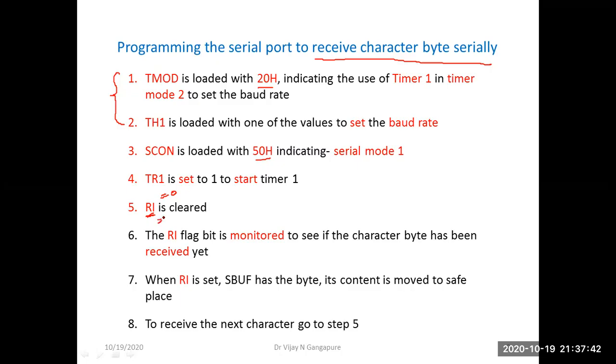So while reception we have to just monitor the RI flag bit, and when it is set, it means that byte is received and available in SBUF.